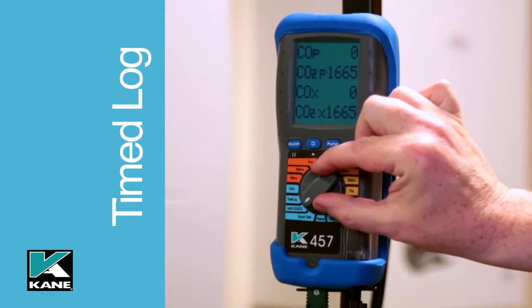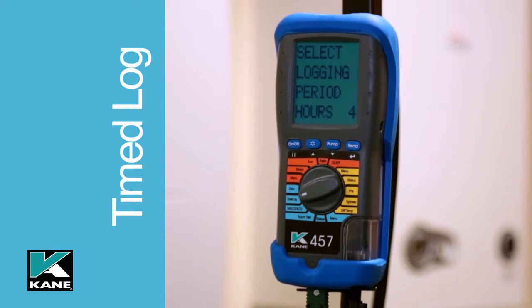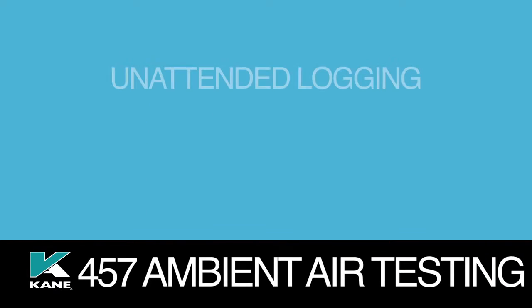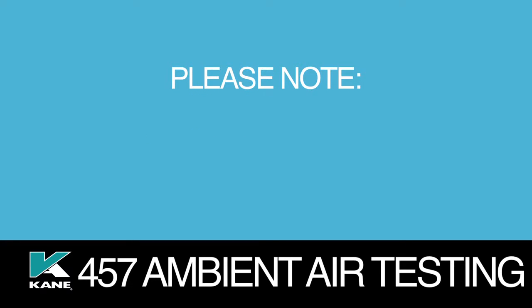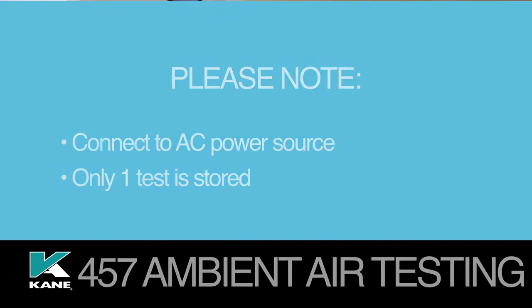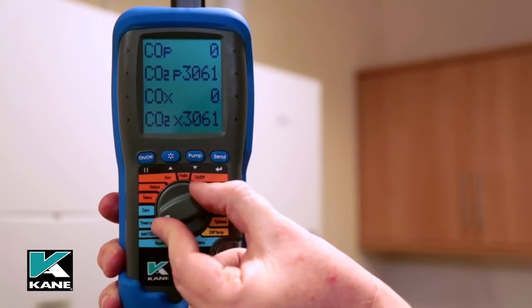There are situations when CO and CO2 readings may need to be taken over specific periods of time to establish a profile of concentrations. The KANE457 allows for unattended timed monitoring and logging periods ranging from 4 hours to 24 hours. Note, for long-term testing, please ensure the analyzer is connected to an AC power source and only one test sequence is stored. To perform the test, select Timed Log.